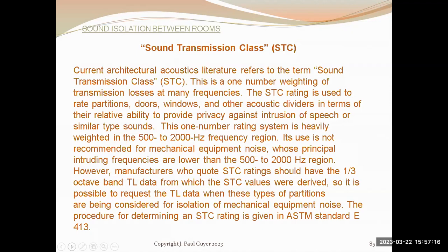So that is a technique that can be used to improve the sound reducing characteristics of your walls. Staggered studs, or double stud wall is even better.